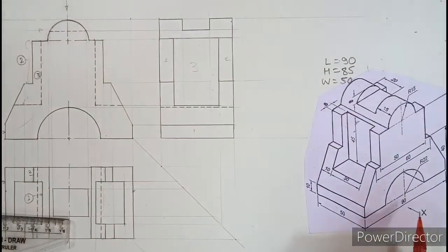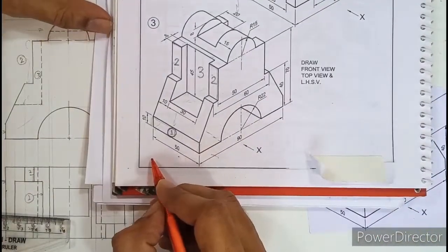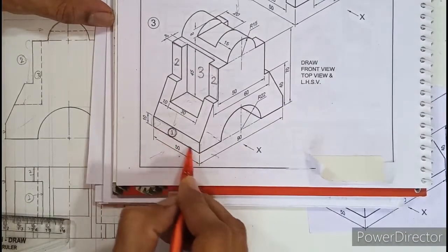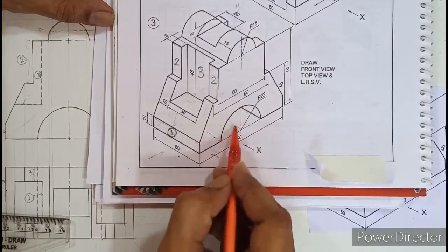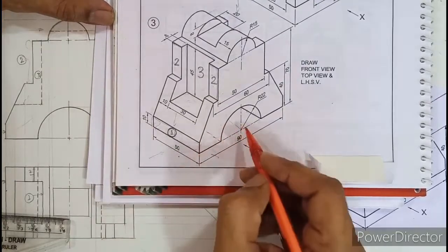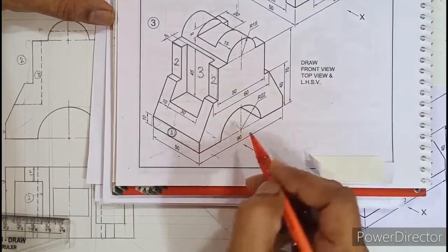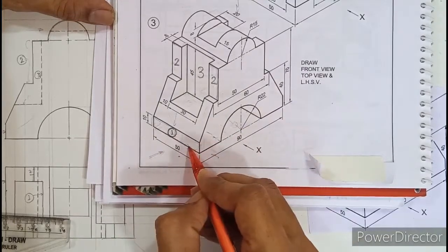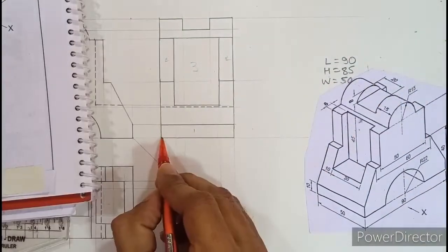Let us talk about the axis now. How to draw the axis in the side view? Look carefully. When you look in the side view from here, this edge at the bottom and the axis going inside, both of them will overlap. Now the question is, if a dark object line overlaps with an axis line, what do we need to draw? When you look in the side view, what comes first? Yes, the object line comes first. So you need to draw the object line here.